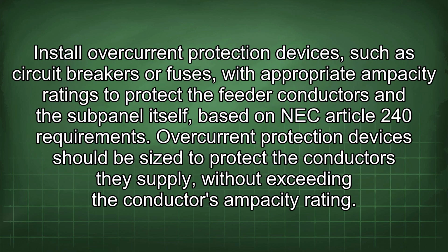Install overcurrent protection devices such as circuit breakers or fuses with appropriate ampacity ratings to protect the feeder conductors and the subpanel itself, based on NEC Article 240 requirements. Overcurrent protection devices should be sized to protect the conductors they supply without exceeding the conductor's ampacity rating.